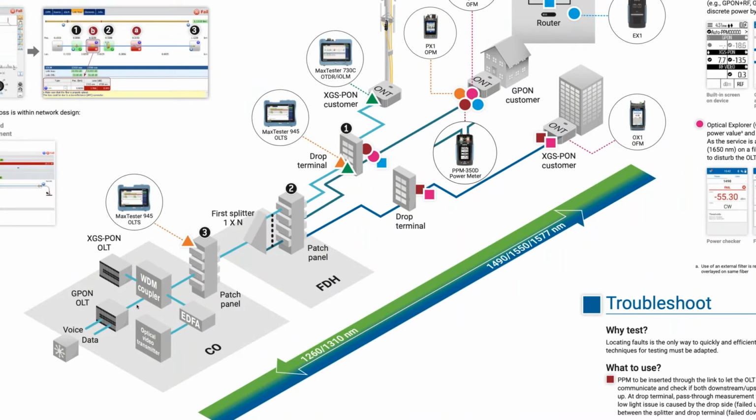Basically, what I started out as is I was shooting from the CO through a single fiber out to a splitter, and then actually to another splitter, and then the 2 different separate legs. And looking in that direction, we get a lot of interesting information because we have different lengths of fiber that are reflecting back at different times. But if I go like I'm doing now, where I shoot from the prem towards the CO, I'm going back to a single fiber. So the reflection that's coming from the CO environment out to the premise is going to be from a single fiber. So it makes a little bit more sense as far as the reflections coming back.